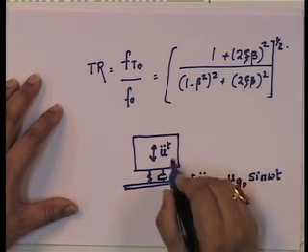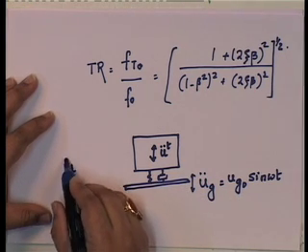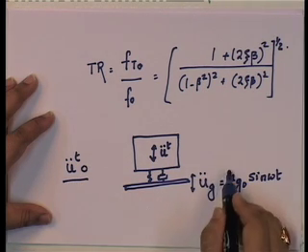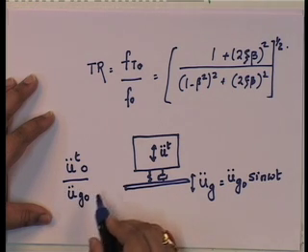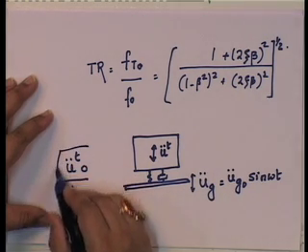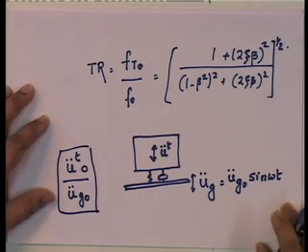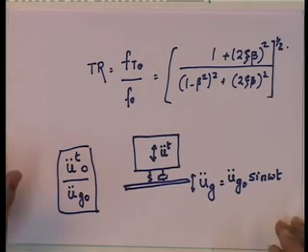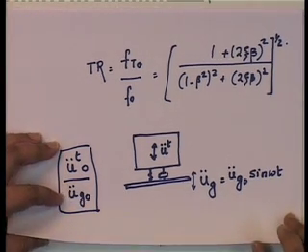Okay. So, the total acceleration, the amplitude of the total acceleration, so I will call that as u t double dot 0, divided by u g 0, this value is also another kind of transmissibility. Okay. So, this value we want to keep it to a minimum. So, let us see how to solve that particular problem, how to write down the equations of motion.